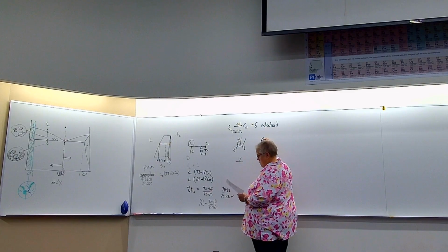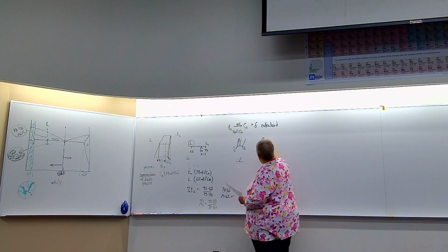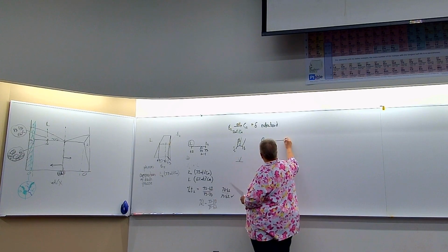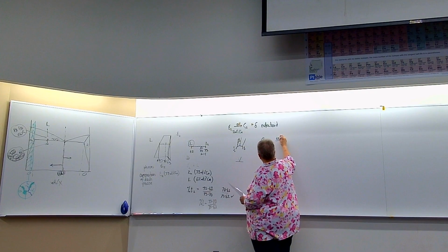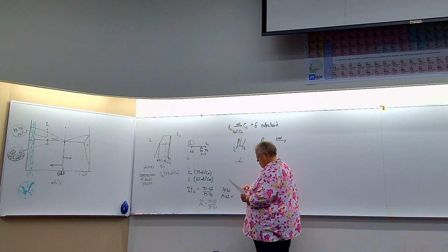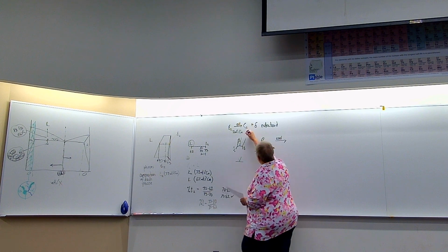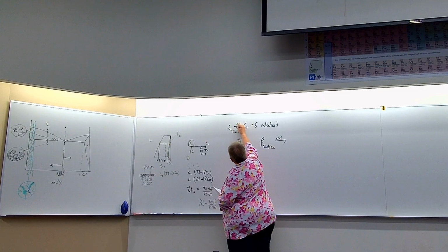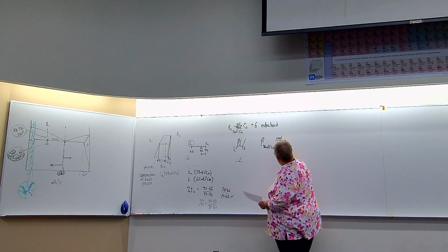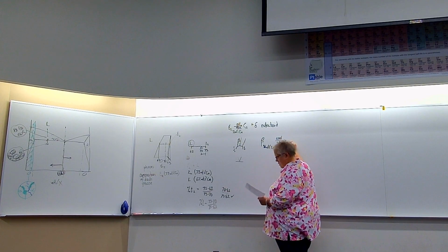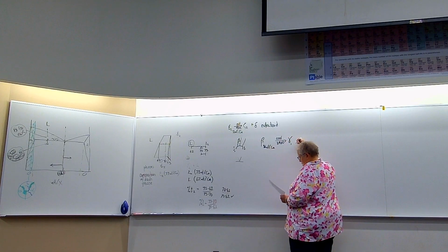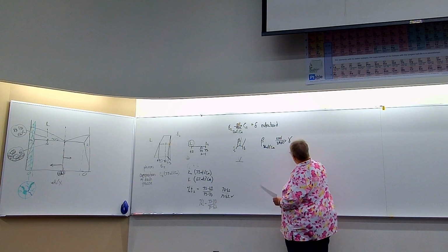Beta at, I'm going to say 86% copper. When cooled, I have to get the temperature. So over here, this was around 850. And here, beta, it's 840. That beta transforms to gamma 1 at, we'll say maybe 83